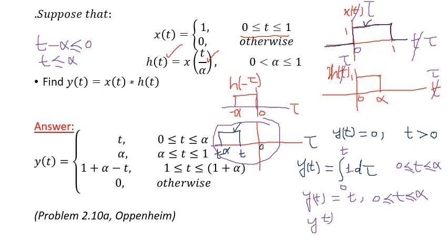You can do this by plotting this signal on your paper, tearing out a small piece of paper and plotting this signal there. And you reflect it, so you get this signal. The important thing is that you make this signal on a separate piece of paper and you slide or shift this signal to the right, and you can observe this very easily.